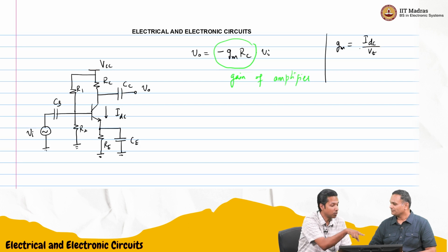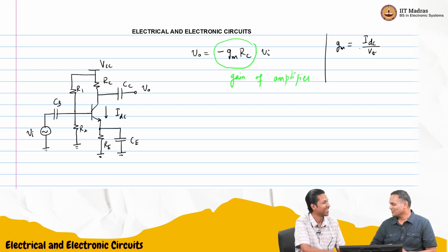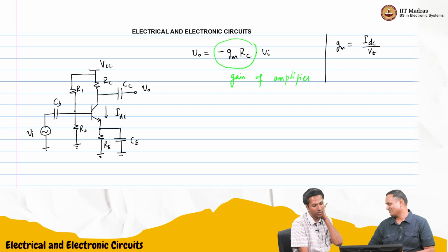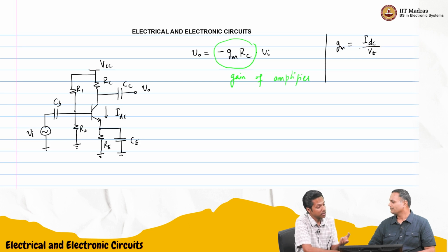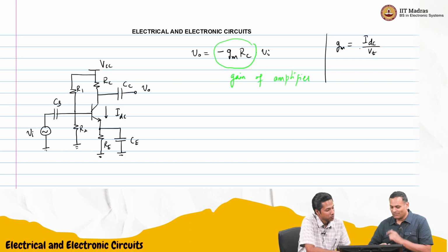Oh, so that's why we have all this resistive network, to try to fix that IDC. I wonder if there is another way to fix IDC. You were mentioning that we may have further gain stages. Everywhere I will have to have this kind of resistive network. I know. So there must be some better way, no?